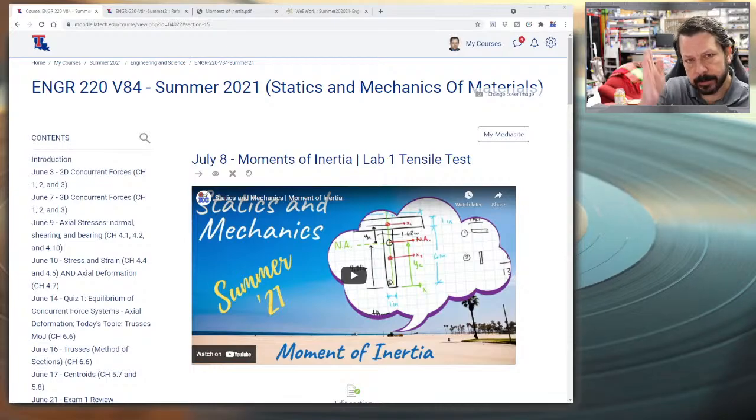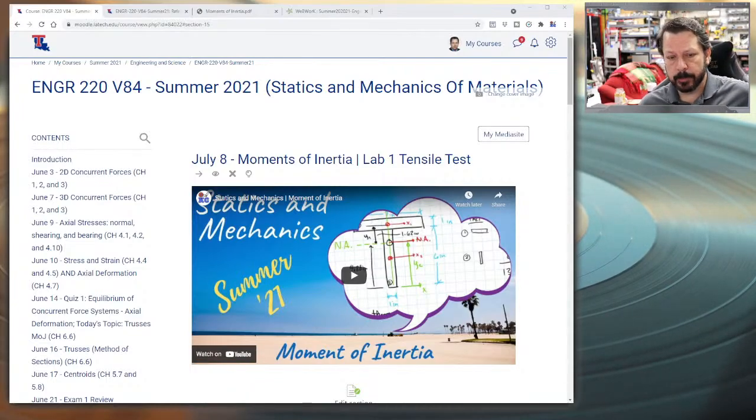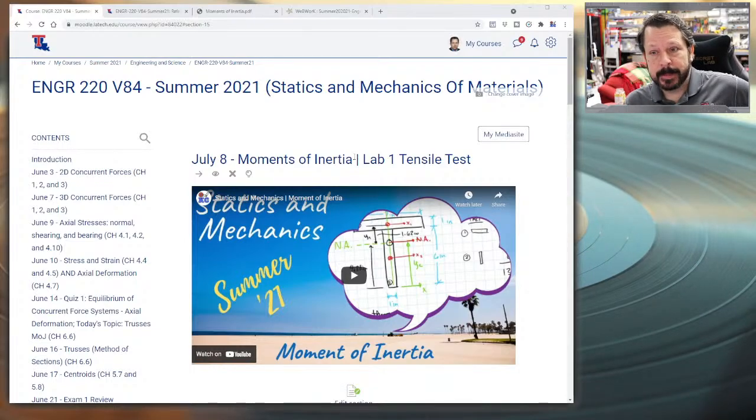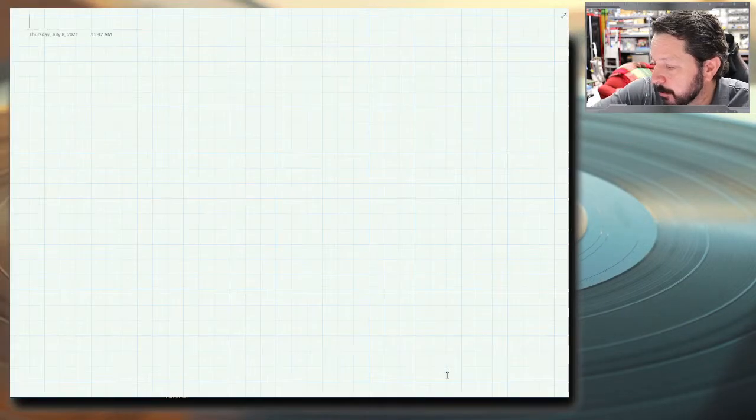We could also chop the beam up at a given spot and find the same thing for that one location. So we're going to do some more of that, but we're going to add on to it this idea of moments of inertia for the beam's cross-section. We talked a few weeks ago about centroids and how at the centroid of a beam's cross-section, we didn't have any flexural stress. There was zero flexural stress. And we drew a picture. Let's look at what we drew, or something like what we drew.